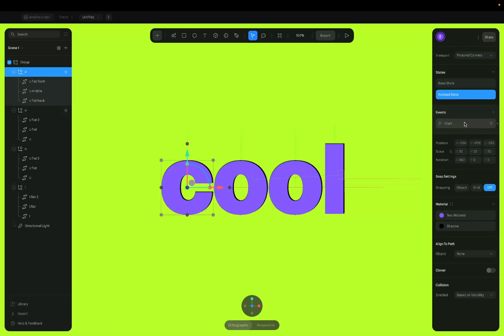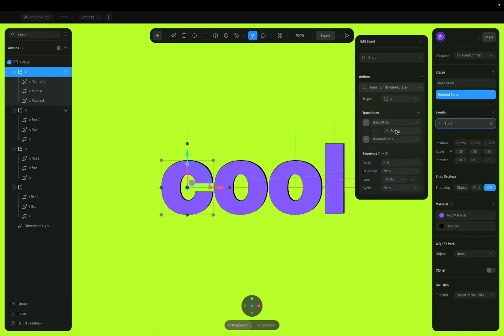To make changes, click on it again and select the spring. The thing about spring is that you can't edit the timing here. You have to edit the spring itself: the mass, stiffness, and so on. So go to the mass section and select 10. Let's add the mass of 10 and the stiffness of 80. Let's just increase the mass and not talk about anything else. Also change the loop here to infinite, so you can continue.